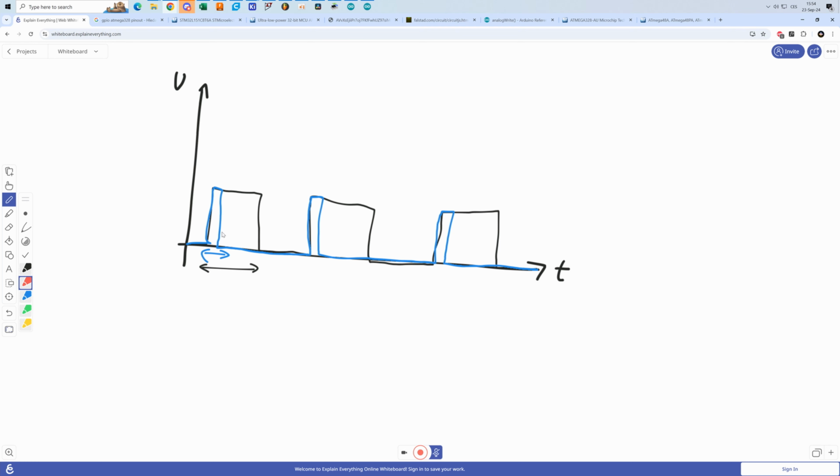If you put some very, let's say, high value in the analogWrite command, you're gonna be generating something like this. You can see that the duty cycle went up drastically, and the pulse width is now even larger. So this is what you're actually doing if you're calling analogWrite command on an Arduino. So you are not generating analog voltage at all. You are only generating the